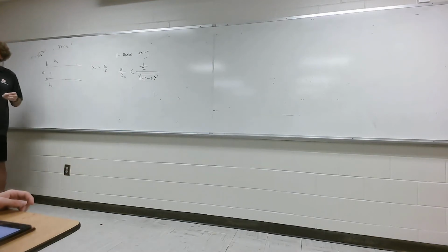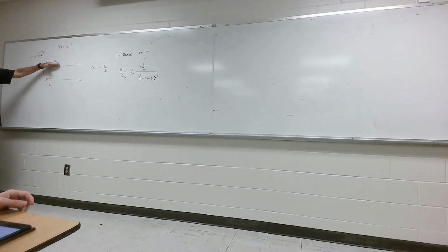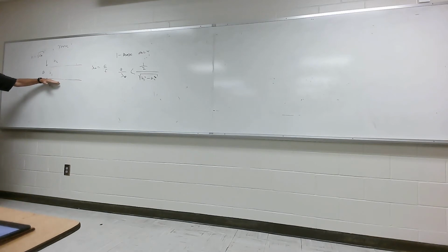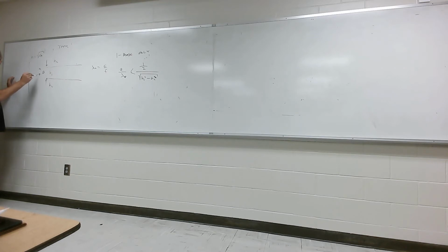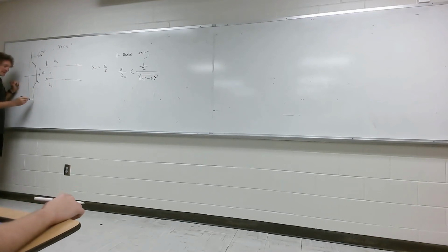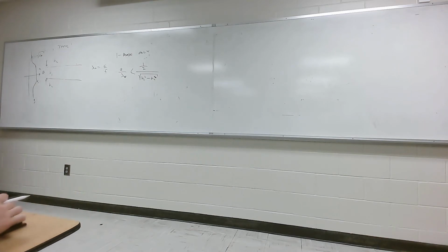And there's something else I got to tell you. Now, in that video, he didn't go through this, but this is called a step index type of slab waveguide or dielectric guide. There are graded indexes where you'll have N1, but instead of going abruptly from N1 to N2, it will gradually go to N2, and you'll have something like this as far as the profile. If this is the value of N, it'll look like this, and then it'll come down to a lower value. This would be N1, and this would be N2. This is called a graded index, and they do have those. There's reasons for that. Basically, a graded index fiber, a graded index slab waveguide, for all intents and purposes, is a lot easier to build when you're dealing with real small dimensions, like submicron to typically micron or less dimensions. They're easier to build.